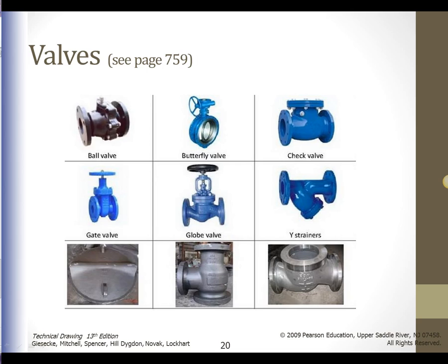Gate valves have a full-size straightaway opening that offers small resistance to flow of fluid, and these valves are used only on low pressure and low temperature services. See figures 21.18 and 21.19 for examples of these valves. Last but not least, when you're talking about valves, or piping in general, the American National Standard Code for Pressure Piping, ANSI, covers information on safety and recommended practices for the various types of pipe used in the industry.